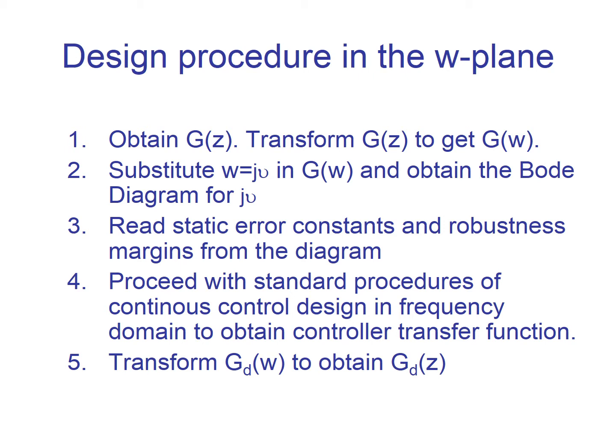Then we proceed with the standard procedures of continuous control design in the frequency domain in order to find a proper transfer function for the controller. Finally, we need to come back to the Z domain in order to implement the controller.